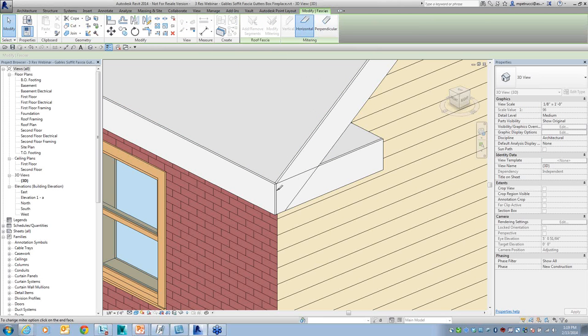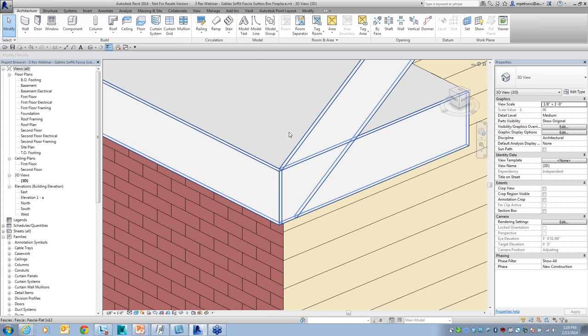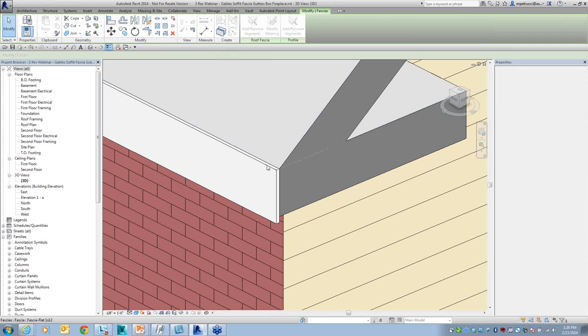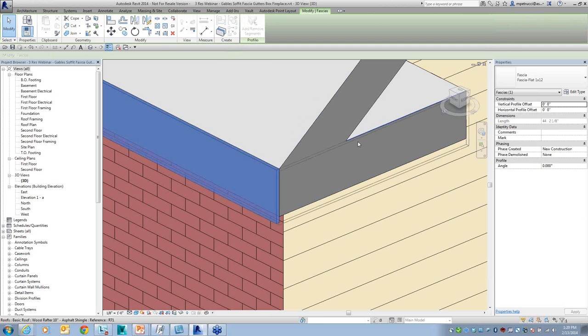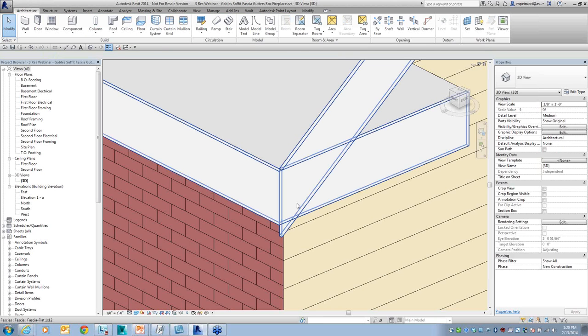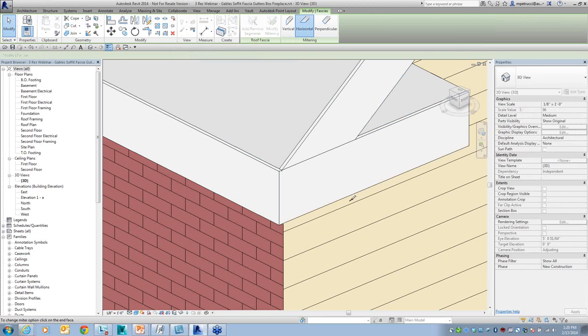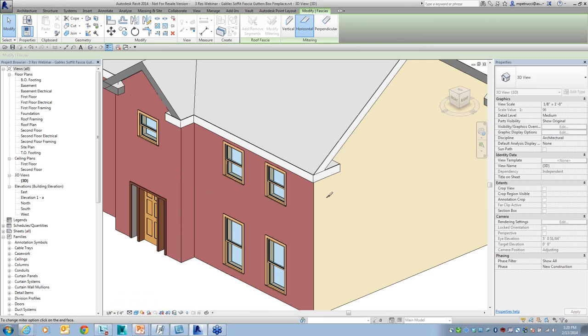And my computer is locked up right here. And I'm going to go ahead and do this real quick here, guys. I'm going to click here, click here. There we go. So I grab this end. So what I'm going to do here is I'm going to go ahead and touch it, I'm going to hit Modify Mitering, and I'm going to go ahead and select that. Now it's horizontal. So now it's been cleaned up. And I can continue doing that around the entire building.